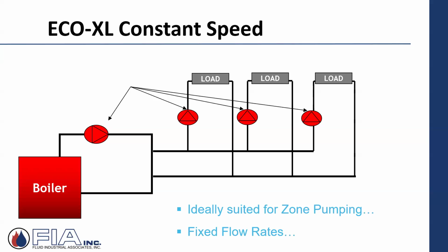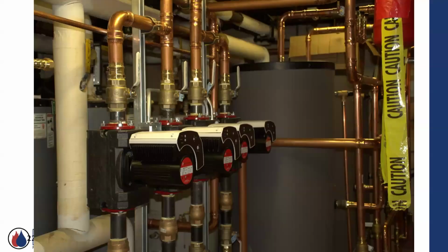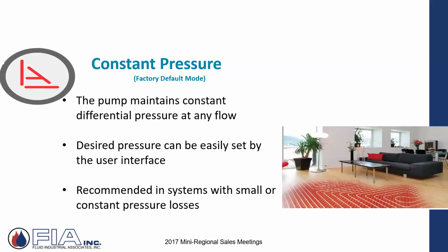This is saying, hey, when I turn on, this is where I'm going. Instead of just getting a pump that's maybe oversized or uses more energy than I need, I can dial that speed down to what the load is. Every time I come on, I don't need to consume more than what I need. So it gives you that ability to dial that in. And constant pressure maintains. Yep.